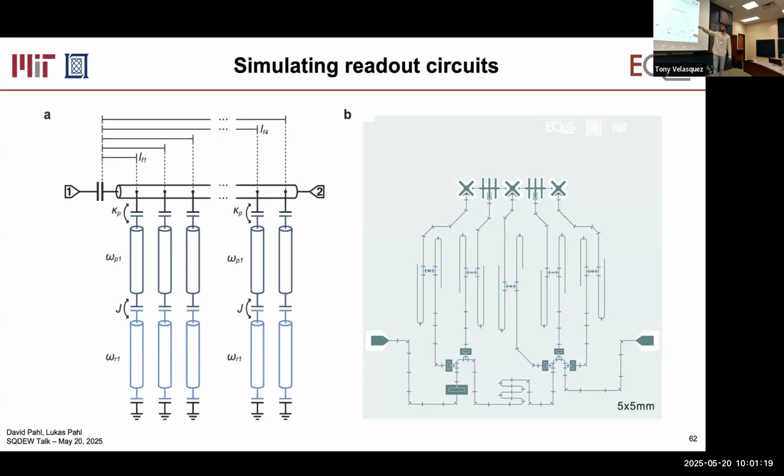And here we have resonators, but pairs of them each, and we multiplex 5 things here. In practice, this can be used to perform really high fidelity multiplexed fast readout, right? This is the architecture we just talked about. Note that I'm drawing them here as half-wave resonators, but they're actually quarter-wave resonators.